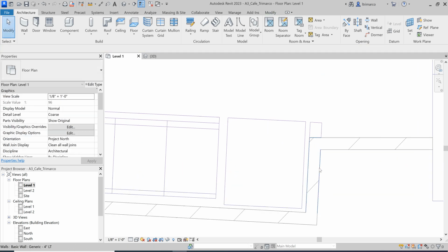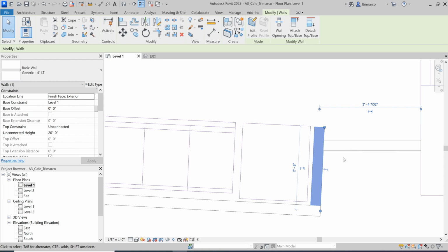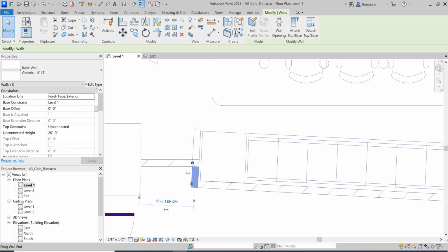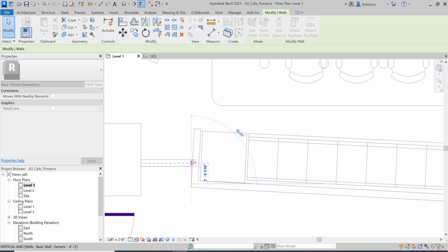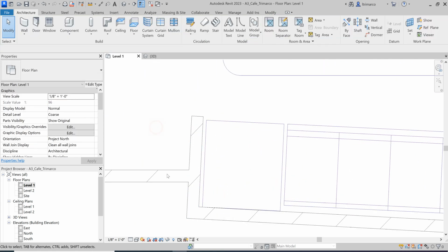And in scenarios like this one where the wall actually extends, let's see what happens if I go ahead and do that. Yeah, these little blue grips, you can snap on them and hold down to drag to extend the object, but sometimes when they are joined with other objects, sometimes that works well, sometimes it doesn't, so I always play a little game. Same thing here, I have the same thing happening with that wall. That blue grip, I'm just moving on top of it, holding down, dragging to the next object snap, and literally it looks like everything looks good.